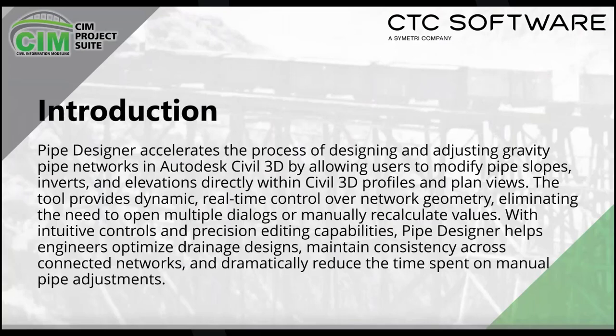So today we're going to be talking about our Pipe Designer tool. It's one of the tools in our project suite of tools, and it's built to help with the design of your pipe networks. We can do a lot of things with it. We can edit slopes, inverts, elevations. We can do all that directly in the drawing with the entire network or selected parts, however we see fit. And then it has real-time control. We can see what's happening. So there's no need to open any of the multiple dialog boxes you need when you're editing a pipe network. I think we all know how cumbersome that can sometimes be.